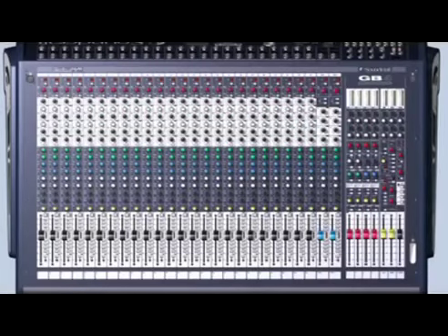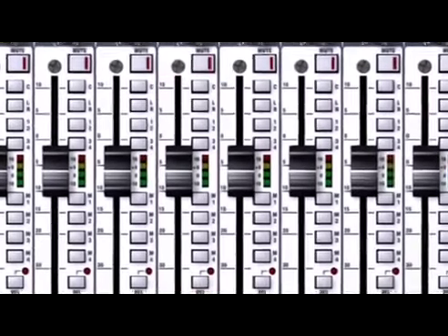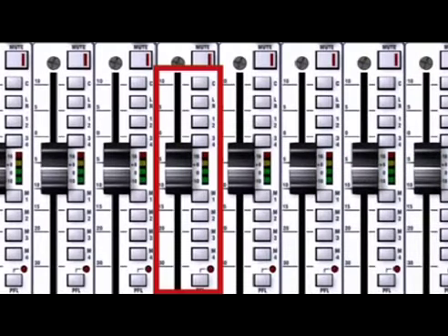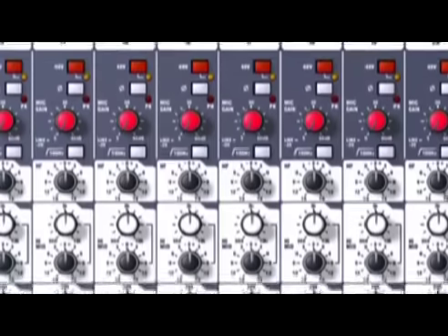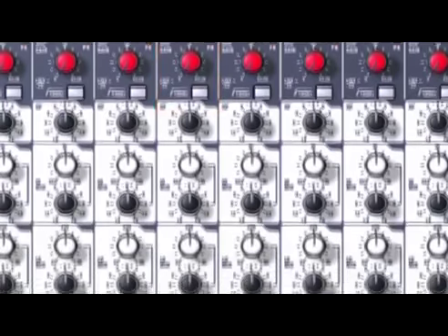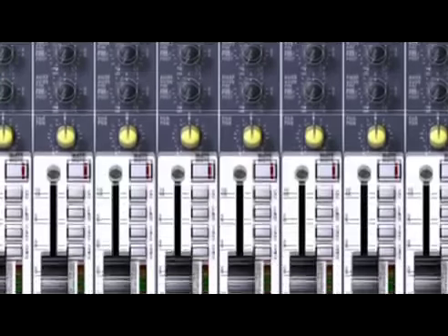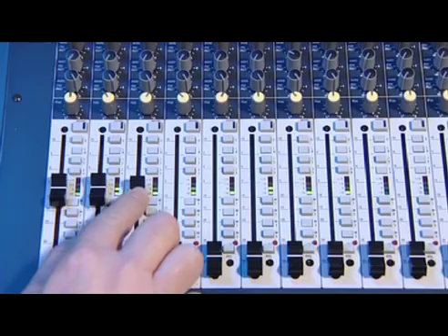Faders set the level of an input signal within the mix. It's important to understand that faders do a different job to the channel gain controls. A gain control deals with a very wide range of signal levels and makes sure that approximately the same amount of signal comes into each channel strip. The fader adjusts the level of audio relative to the other channels.